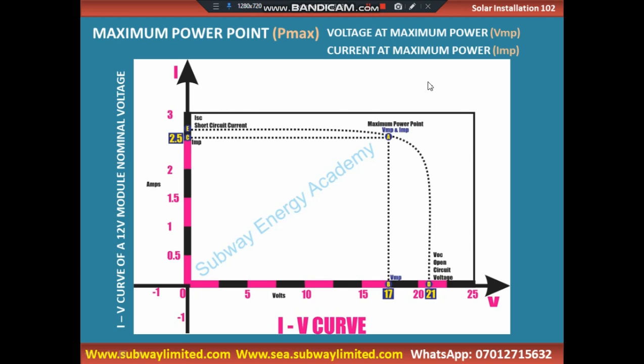So the maximum power point is the point where your solar panel will produce its maximum output power under load. Remember, this is very important. You have to make sure that your solar panel is under a load.